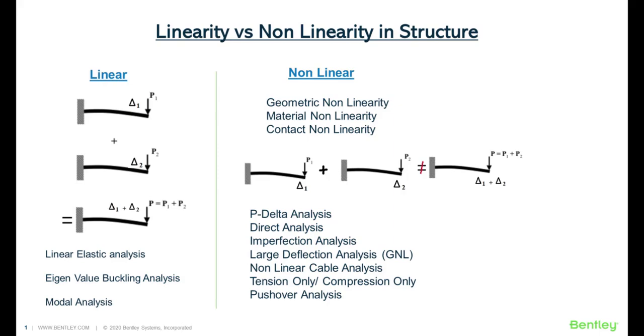That means as it's linear, you can linearly superimpose the primary effects. In that case, you can use the load combination. But if your structure is behaving nonlinearly, for example, you have invoked some P delta effect, you have invoked direct analysis, you have invoked tension only or compression only members or compression only supports, these are basically not linear, they are behaving nonlinearly.